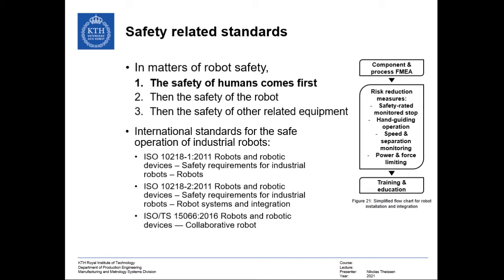And then there is the automatic mode, in which you can no longer control the robot from the teach pendant, but only through the task program, and the robot is allowed to move with its full velocity, or that is at its highest velocity, which for the robots that are currently commercially available might be up to about 1.5 or 2 meters per second.